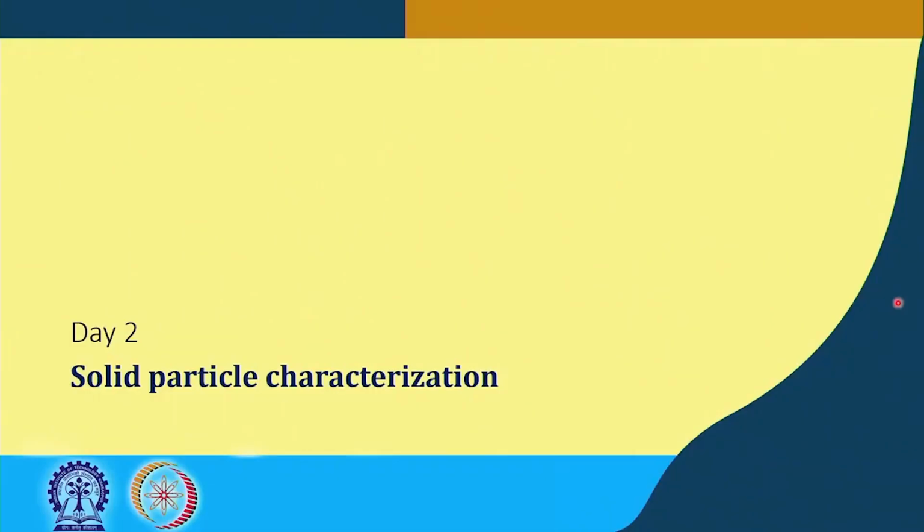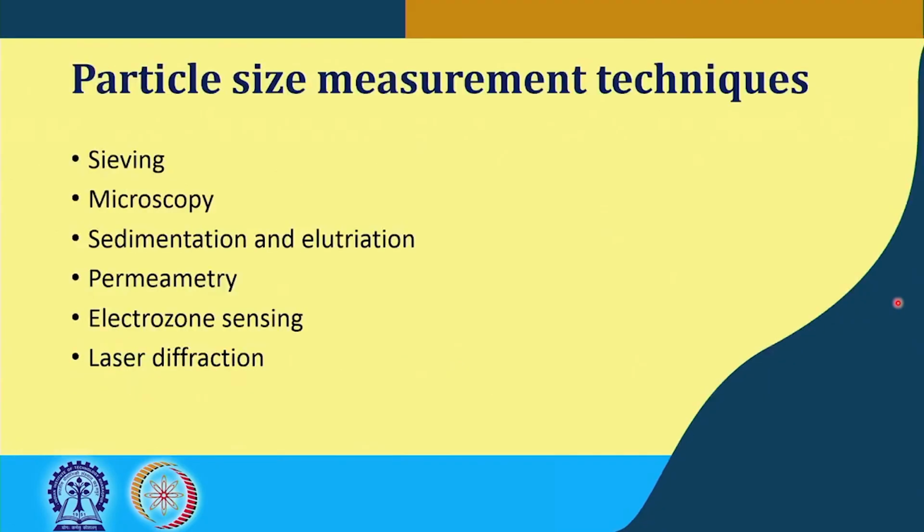Today we will go through the solid particle characterization that we started on day 1. At the end of day 1, I mentioned that particle size measurement techniques will be covered in this class. Those I mentioned by name as well are sieving, microscopy, sedimentation and elutriation, permeametry, electrozone sensing and laser diffraction.